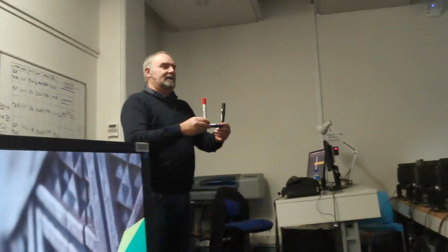So that's your U-bar, right? But when you look down on it, you just see a donut on each end, don't you? So that's how we show the bar, but we can't tell whether it's coming up to us or whether it's going down that way. So that's why we should always show 2 views of reinforcing.